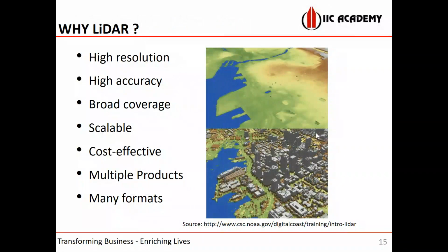Why people are using LiDAR is that it has high resolution, because as you already know, we can get even 5 centimeter accuracy data. Spatial resolution is 5 centimeter; any object on the Earth surface of 5 centimeter we can identify, and it is more accurate. It will cover a broad area, since we are doing the survey from a higher altitude.